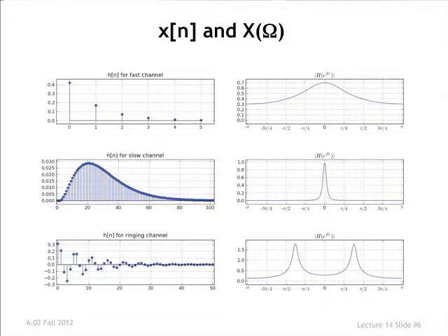All right? You can also start to develop ideas for how high a frequency you ought to expect to see here. So for instance, what's the fastest wiggle that you see in this signal? If you were thinking of underlying sinusoids, about how long does it take for the fastest wiggling you're seeing over here? Well, to my eye, this kind of rises and curves within about 18 or 20 samples, right? So this might be a half period of an underlying sinusoid. So if I thought of the period as being,